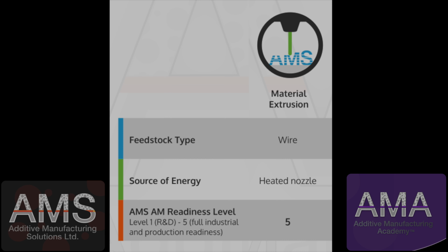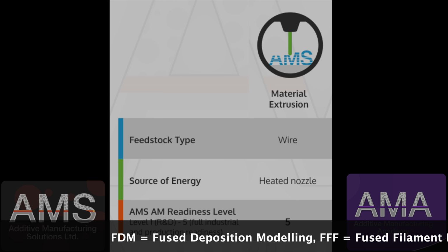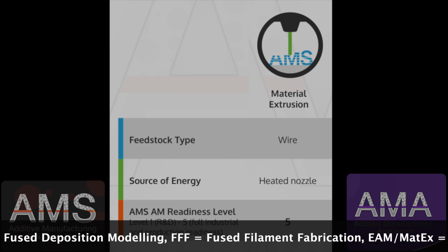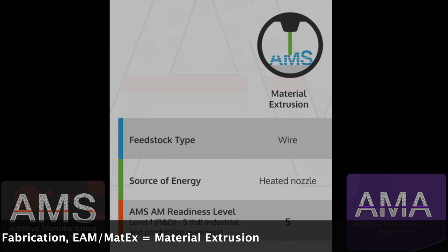Next, we have material extrusion. In this case, material extrusion may also look quite familiar to any other technologies that you've maybe seen in schools, colleges, or even for sale in supermarkets these days. Material extrusion uses a plastic wire going through a heated nozzle and is often called FDM, Fused Deposition Modeling, or sometimes FFF. These technologies are all using polymer wires through a heated nozzle to create a malleable process where the deposit of plastic wire is selectively added in the shape made by the extrusion head.